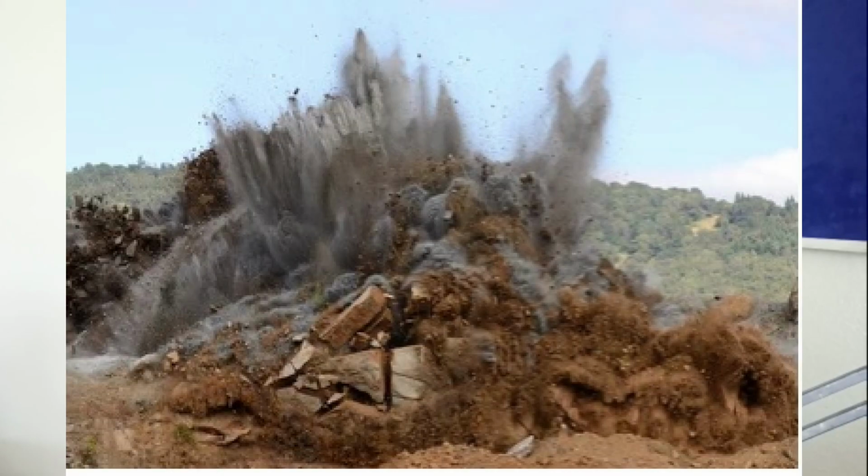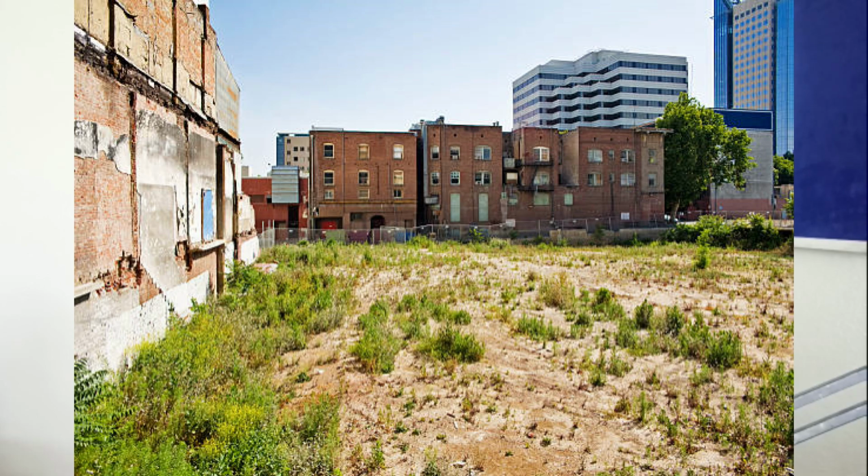Why is this first method only applicable there? Because whenever explosion or blasting is done, foundation disturbance happens. If existing buildings are there, there is a chance of the structure getting weak while blasting, and the surrounding site will be affected. That is one precaution you have to take. So this explosion method is only applicable where the surrounding site is free from existing buildings.